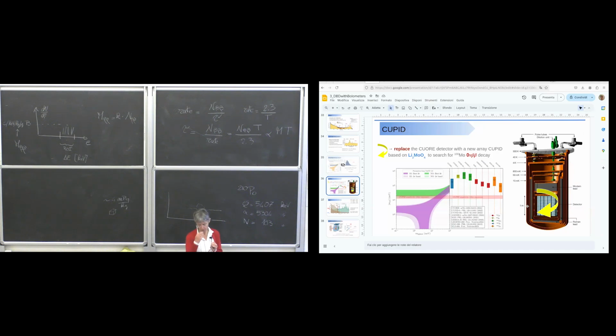And because copper is produced for its electrical properties, you need to have a very clean copper. And so when you remove impurities that compromise the conductivity, you also clean out most of the impurities. But the problem is what I've mentioned before, that is the possibility that you have hydrogen inside the copper.